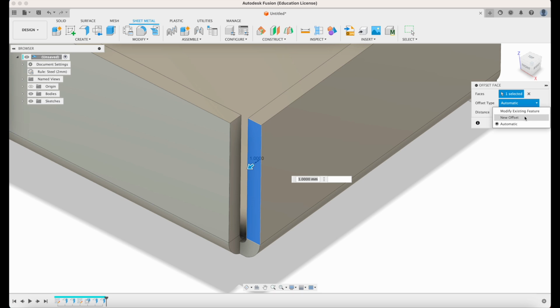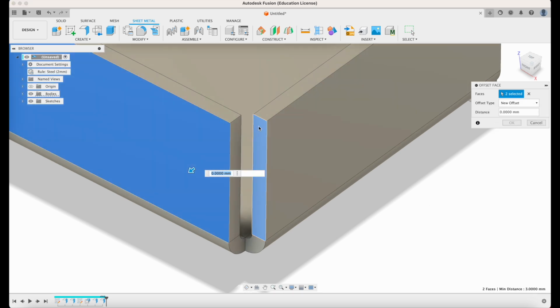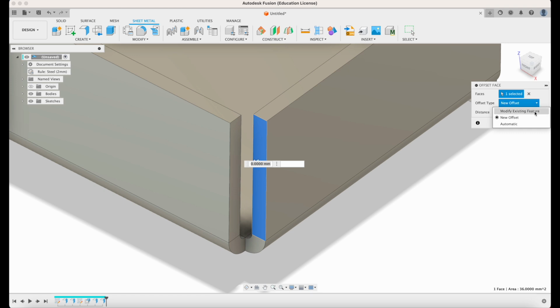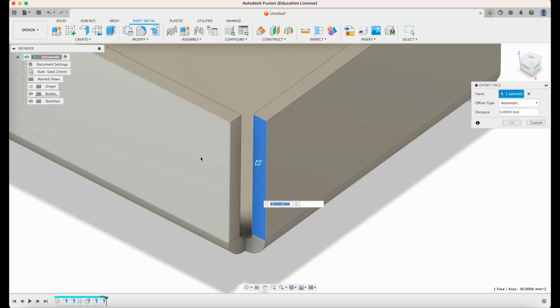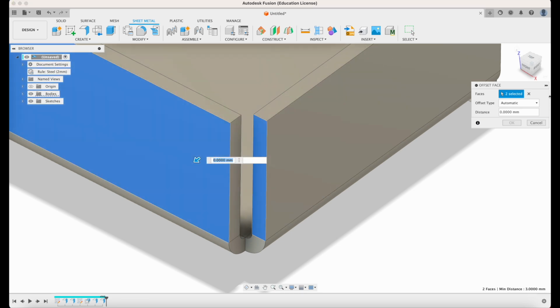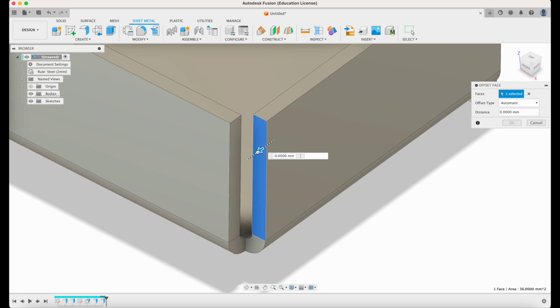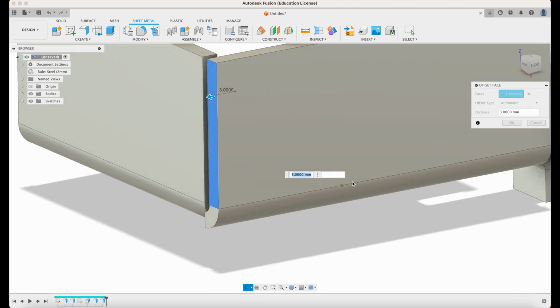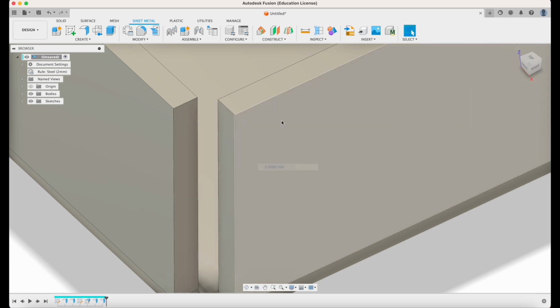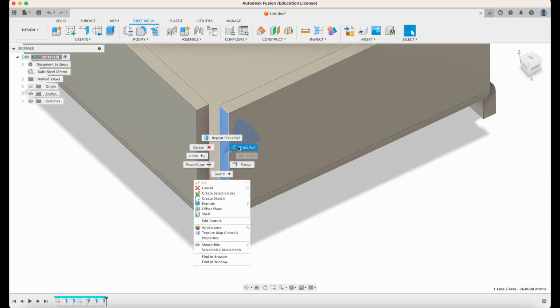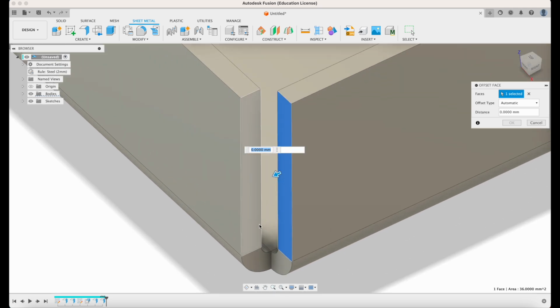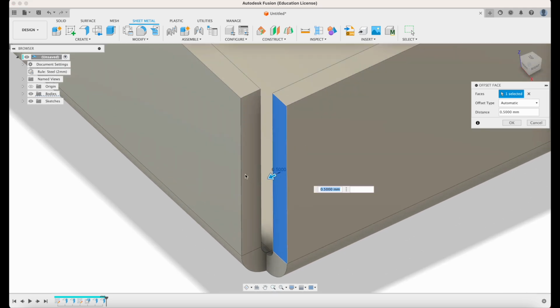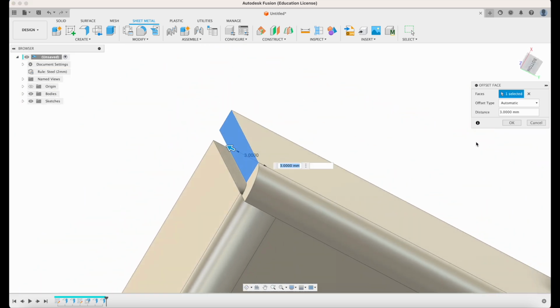And I can do that by using offsets, for example, or modifying existing features, automatic, okay? I can say extend this piece to this plane. And the way I do that is I have to first select press and pull, then before I select the face that I want this to be offset to, I have to move it a little bit. Then I can say, okay, do that.